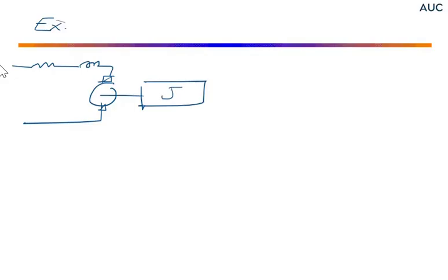the electromechanical system that we have considered, which is composed of a DC motor driving a mechanical load of inertia J with friction in the environment, this is called B. If I apply an input Ei to the circuit, which is composed of a resistance and an inductance, this will be corresponding to the winding of the motor.